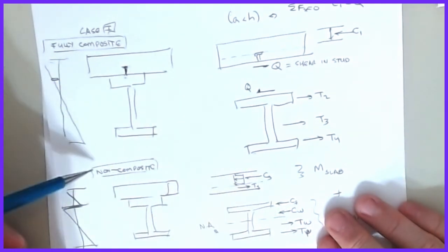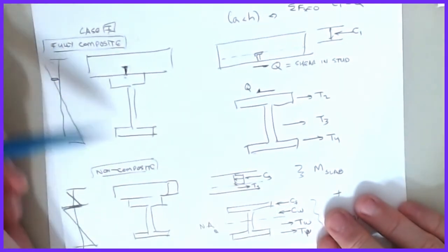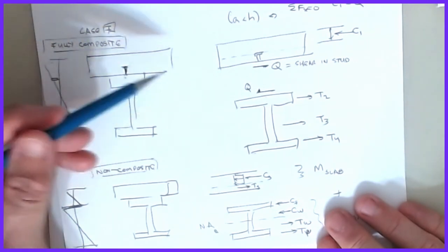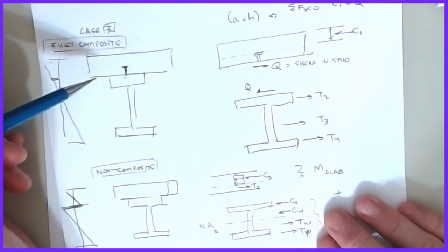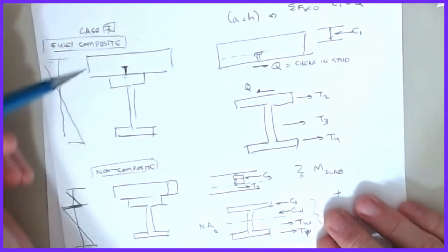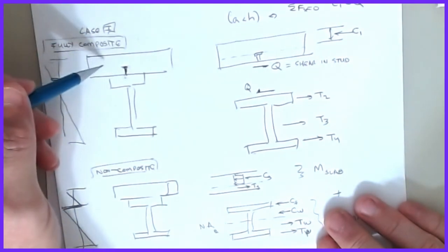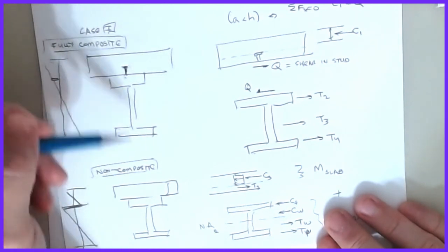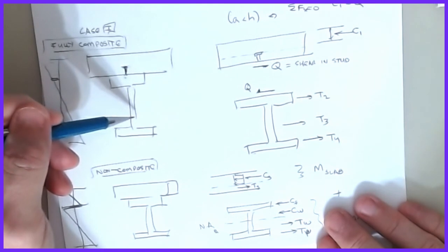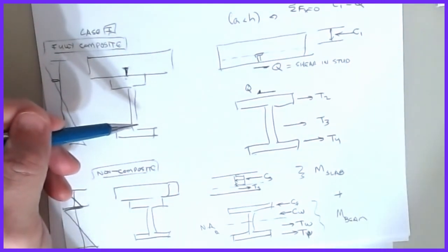One of the things that makes this guy a little bit more complex, actually makes both of them more complex, is something known as shored construction. And this is the reason I was asking, that if I count on the slab doing some of the work on this, I have to hold this beam up in place until the concrete hardens. I have to provide bracing underneath it, right?